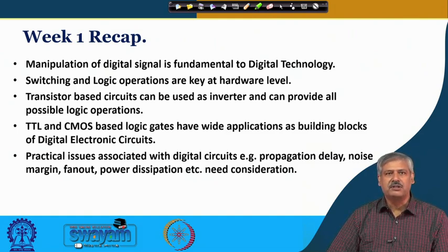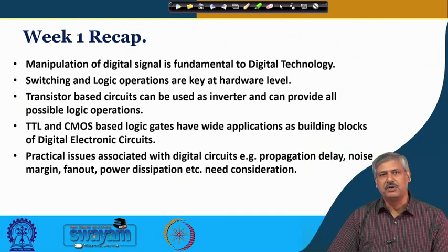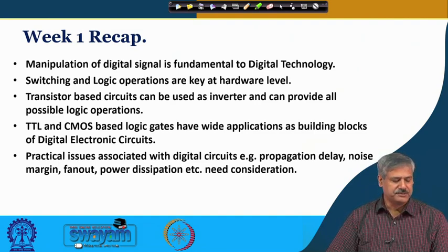Transistor based circuits are important for realization of these switching and logic operations, because we get inverting operation through transistors. TTL and CMOS based logic gates have wide applications as building blocks of digital electronic circuits. And you also remember that there are practical issues like propagation delay, noise margin, fan out, power dissipation, and so on, which need consideration when we develop digital circuits or complex digital building blocks.